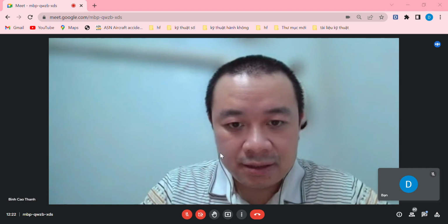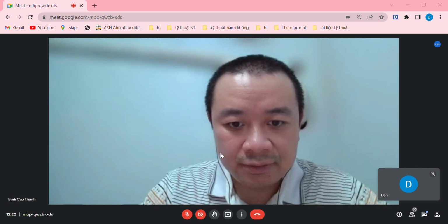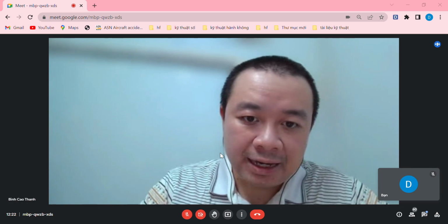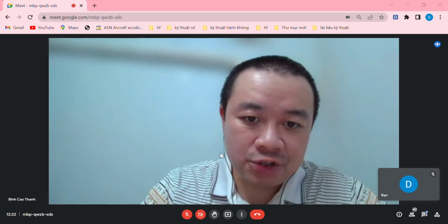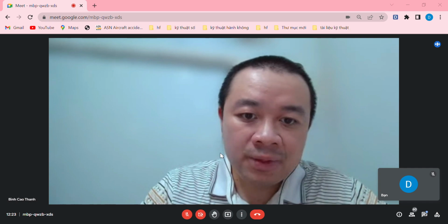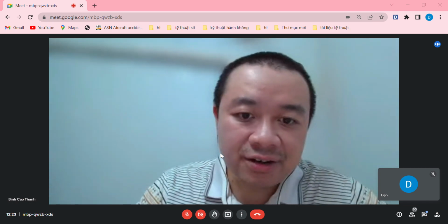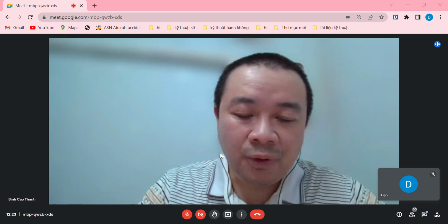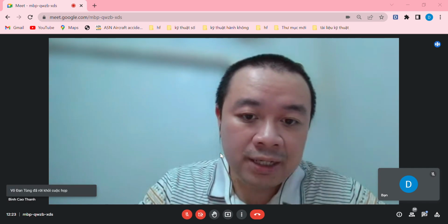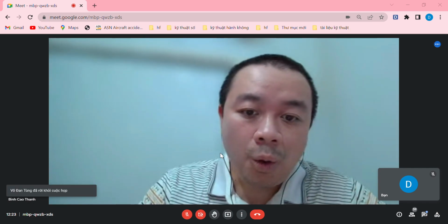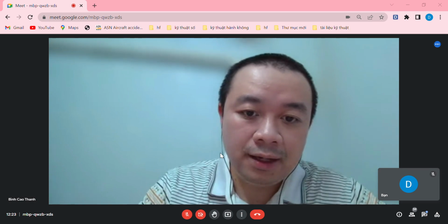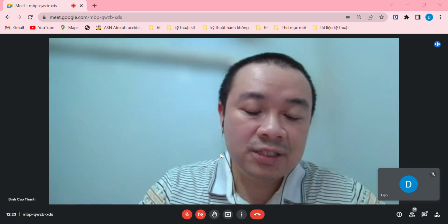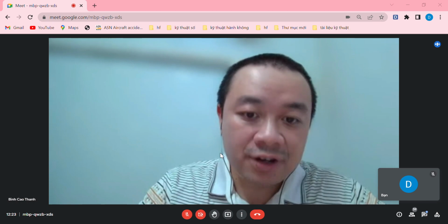And the second figure shows here the optimized model after running the FE analysis. And you can check it against the allowable stress and strain. You can perform a fatigue test to see how many cycles the new component can withstand before it is damaged, or before the initial crack occurs on the most critical surface of the part, because cracks tend to occur there first.